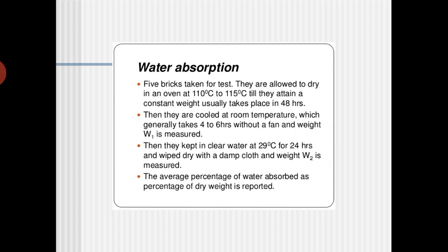So how do we judge the water? It may look like clean water, but you have to test it with a conductivity meter. The conductivity should not exceed 100 microsiemens per centimeter. Normally the conductivity of distilled water is in the range of 50 microsiemens per centimeter. If it is more than 100 microsiemens per centimeter, we will not use that water for the immersion because the conductivity is high.